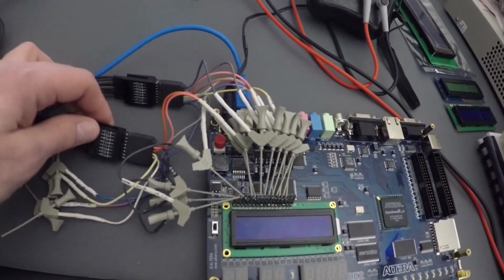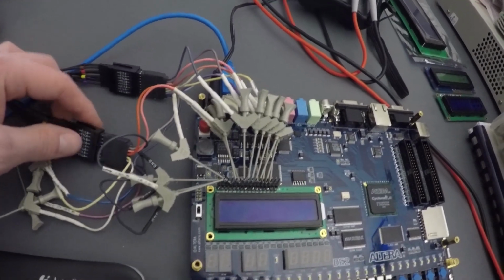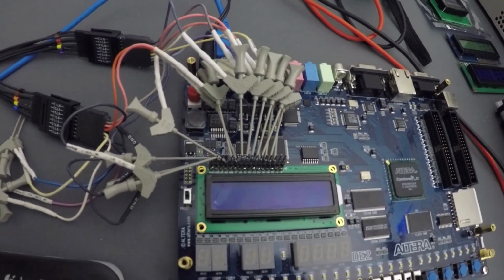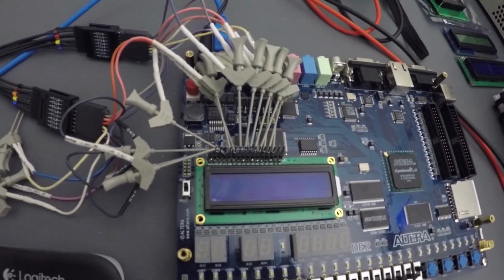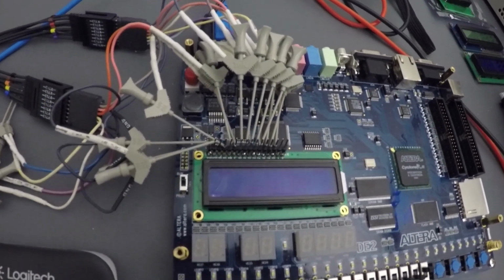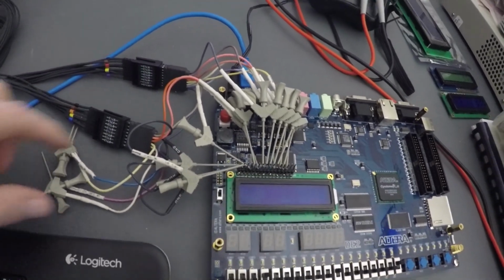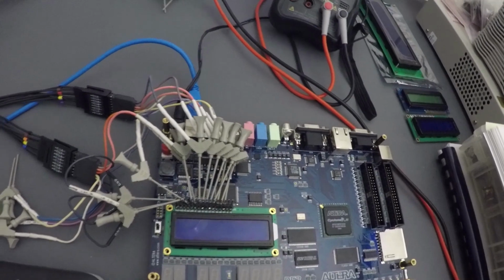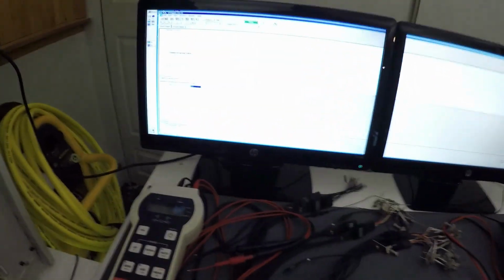And then on my D2 probe, I have the control signals. So I have our RS, our RW, our enable, and we can monitor all those and view those in relation to the databus, and we can view that simultaneously on our waveform.